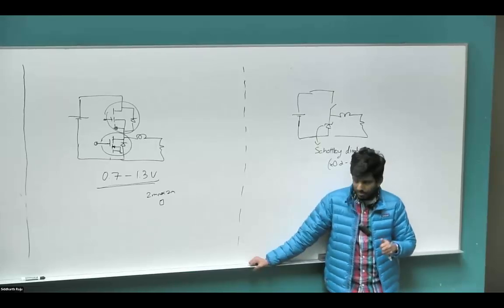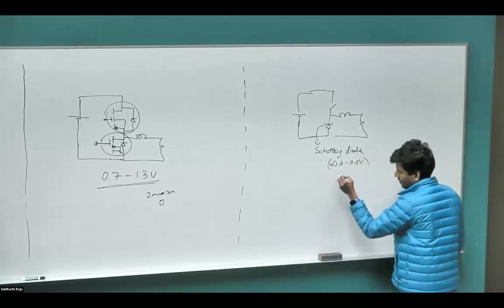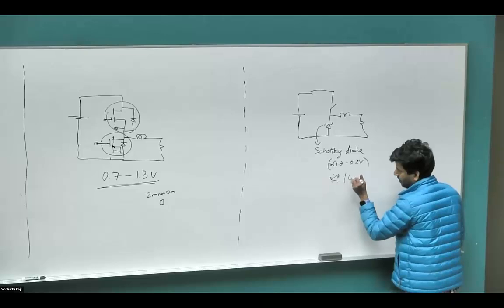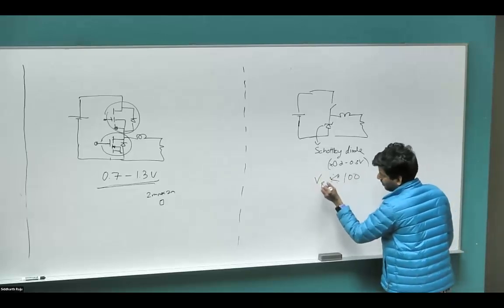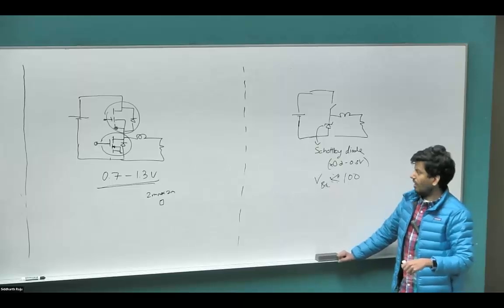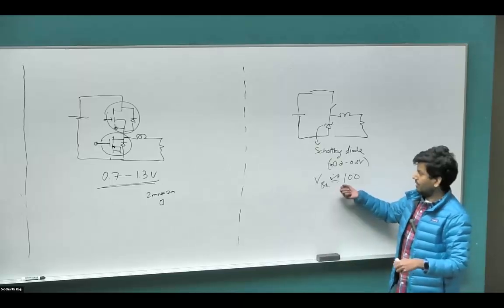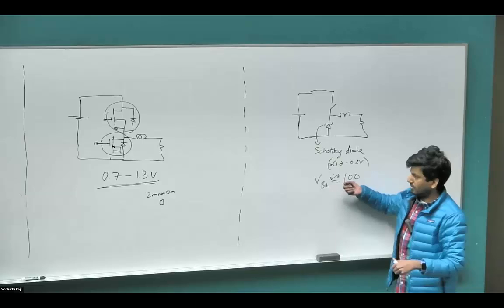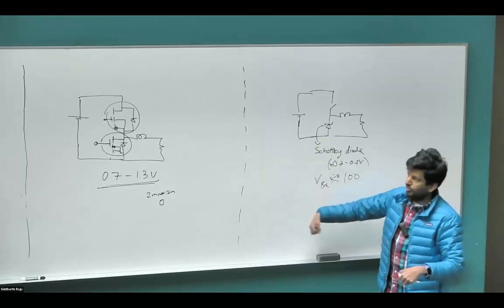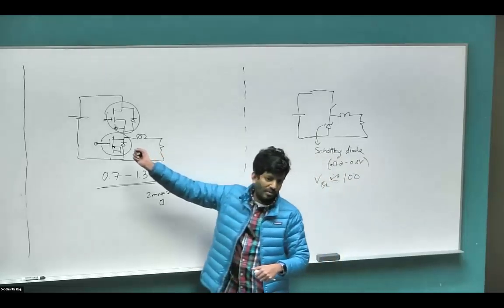Breakdown voltage. So typically you can't find a Schottky diode with a breakdown voltage greater than 100 volts. Okay, so that's where the limitation comes. So when you have a high voltage application, let's say 480 volts or 400 volts, 600 volts, DC bus or something, there is no way you can put a Schottky diode in those applications. So you would have to go to a power semiconductor diode at that point, right?